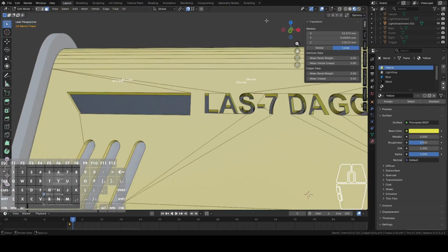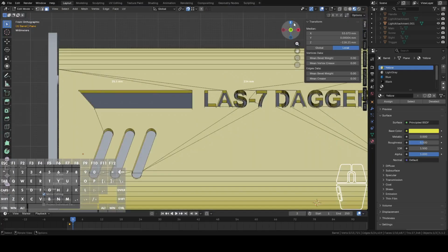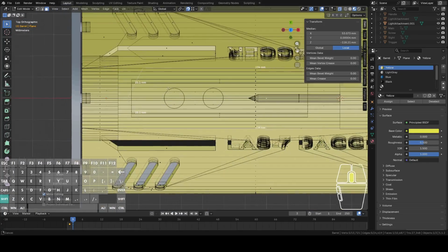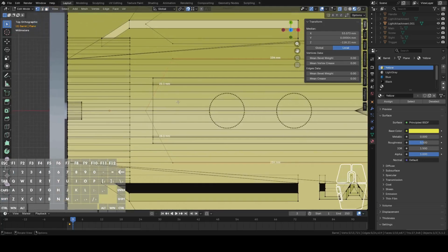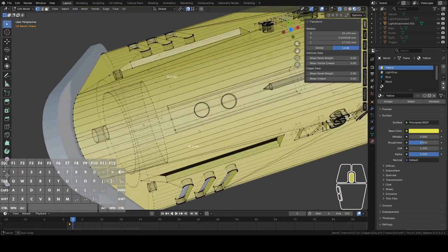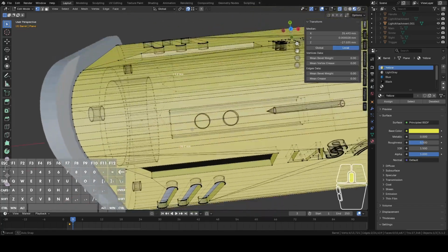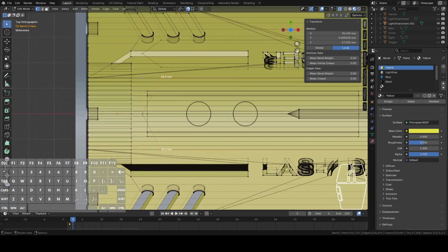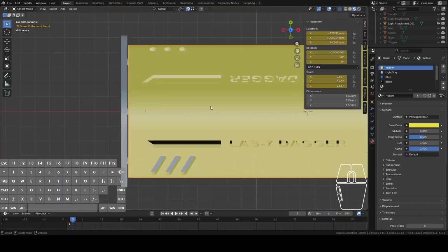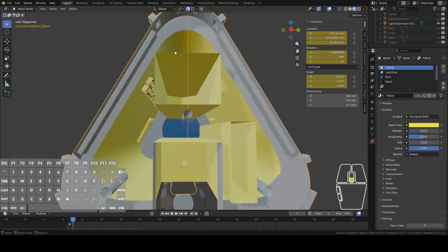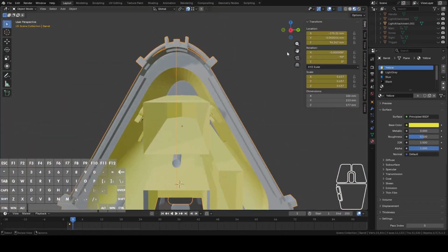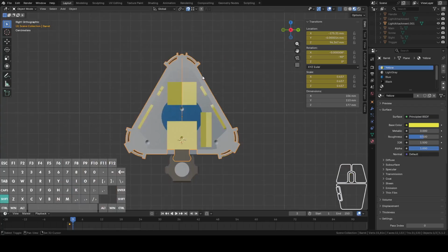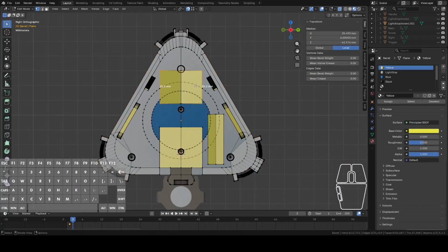Let's see if that's about a 45-degree angle. It might not be now that we scaled it out. Yeah, definitely not. So let's get these two parts of that roof shape, and then let's G X to bring it down. Try to make sure it's at a 45-degree angle or more, because most printers will be able to print that kind of overhang without the need for support.